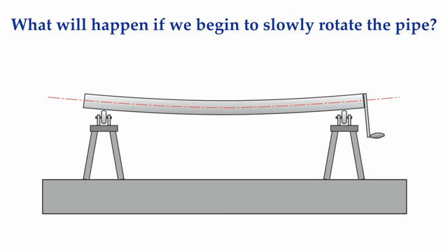But for long spans between bearings, as might be found in the armatures of large electric generators, it is not uncommon to have a sag of 50 to 100 thousandths of an inch or more. This perfectly natural elastic bending of shafts needs to be taken into consideration when aligning two or more shafts where each shaft has a considerable span between the bearings, both of which are elastically bending due to their own weight.